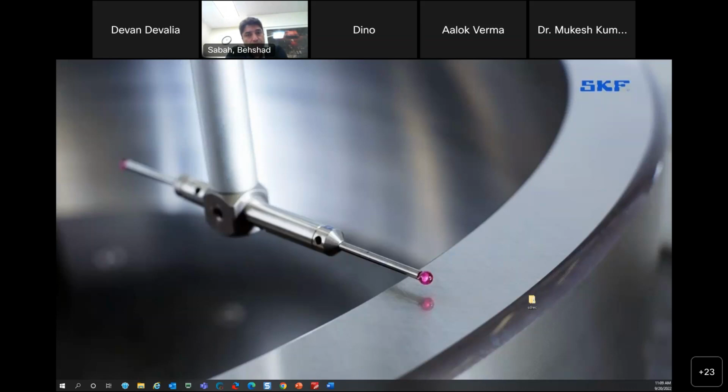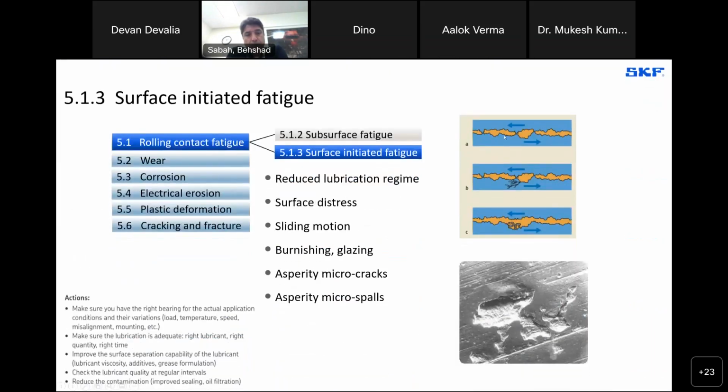The desired effect is that we want a cleaner break when we have boundary lubrication. We want these tips to break off cleanly, and to do that, the EP weakens the surface of the steel. I guess I repeated myself a few times, but I hope we got to the explanation.